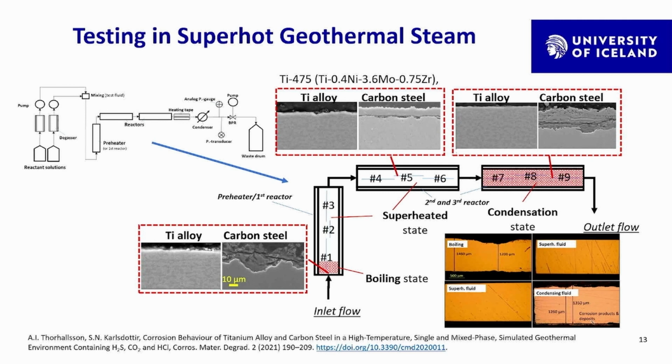And we tested a new titanium grade, the 475, which has good potential and has been recently developed by TIMET, or Special Metals, PCC, and which performed well compared, of course, to the carbon steel, which you can also see from these cross sections here for the boiling state and the condensing fluid.